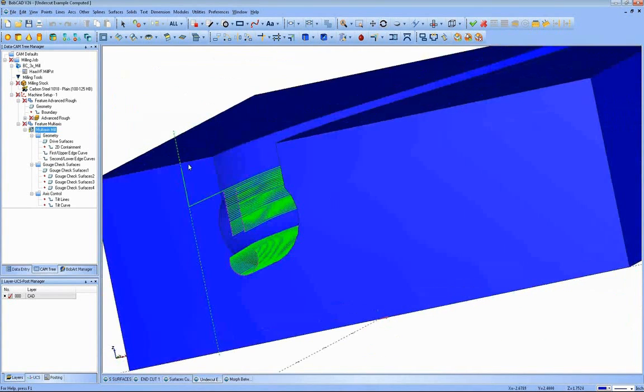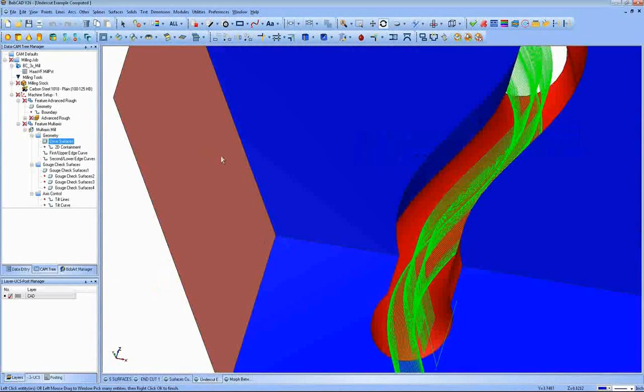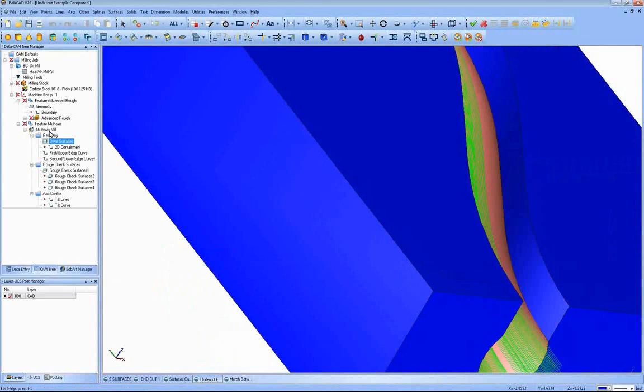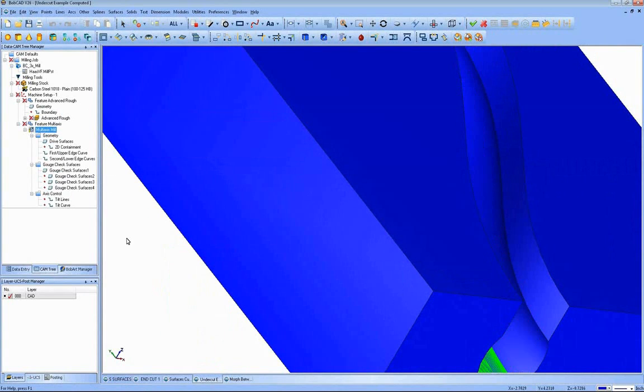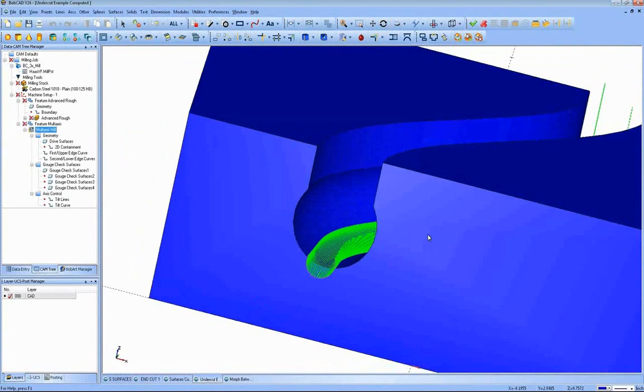You can turn on the roughing, just like we've done in any of the past. Drive surfaces, reselect. I'm going to turn that one off, and that one off, and recompute. And as you can see, if you're curious if that might be a better cut for you, it just takes a couple minutes usually, depending on the toolpath calculation times, to change the surface selection and recompute it. Take a look at the new toolpath.